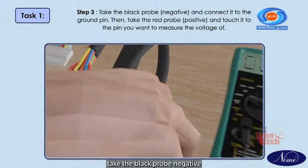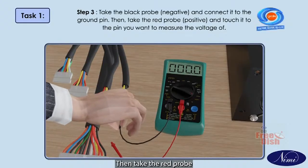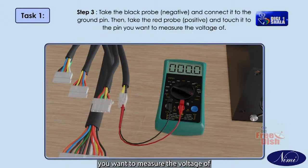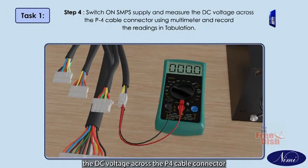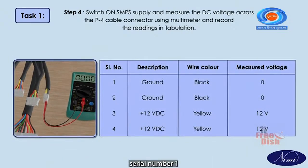Step 3. Take the black probe, negative, and connect it to the ground pin. Then take the red probe, positive, and touch it to the pin you want to measure the voltage of. Step 4. Switch on the SMPS supply and measure the DC voltage across the P4 cable connector using a multimeter and record the readings in the tabulation.